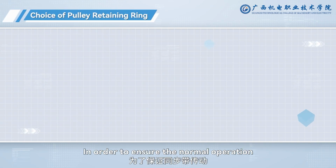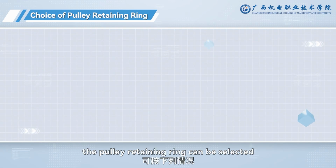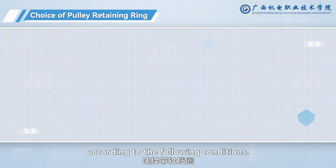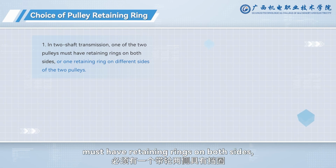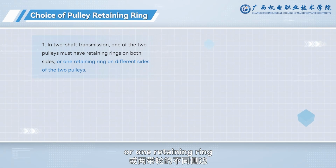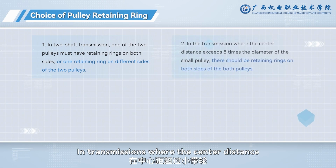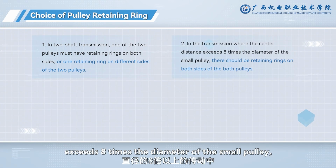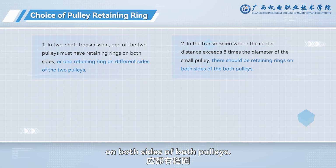In order to ensure the normal operation of the synchronous belt drive, the pulley retaining ring can be selected according to the following conditions. In a two-shaft drive, one of the two pulleys must have retaining rings on both sides, or one retaining ring on different sides of the two pulleys. In transmissions where the center distance exceeds 8 times the diameter of the small pulley, there should be retaining rings on both sides of both pulleys.